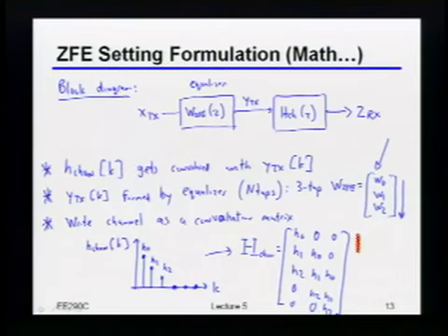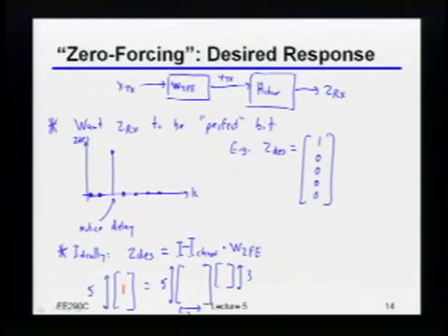Okay, I guess, right? For equalizing on the transmitter, time is relative to the transmitter. So you have to be careful. In this thing, if I put a 0 right here, you still would have needed to shift your z desired, right? Because the z desired is coming out on this side. If the channel itself had delay in it, then you'd have one symbol of delay in that z desired over here just from the channel. Does that make sense?